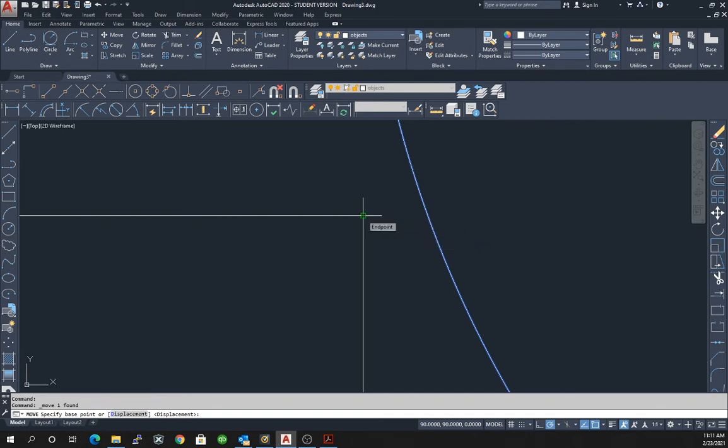We're going to take a tracking line from this endpoint. So we start at this endpoint. I haven't hit my mouse button. I slide it over, and at the point where I get my intersection, I hit my mouse button. So that gives me the point that I'm moving at.